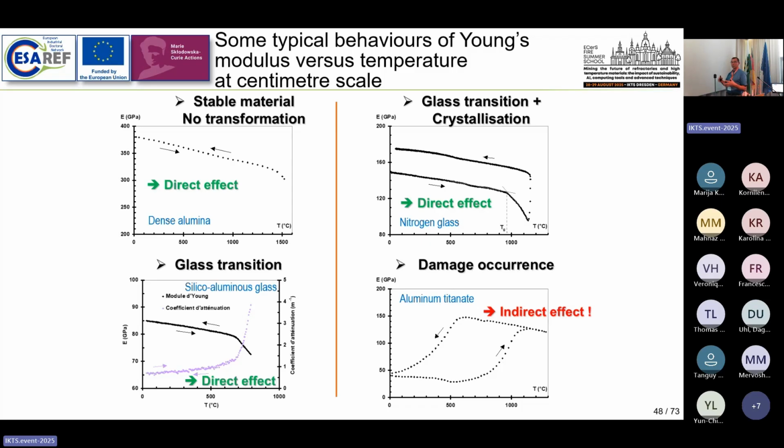And this is a material which is well known for thermoshock because of the quantity of macro cracks which are introduced in the material due to the CTE mismatch between the different crystallographic axes of this orthorhombic architecture. And this is a very pedagogical curve to demonstrate how a material behaves when it is not subject to any evolution in chemistry, density or porosity, just crack evolution.